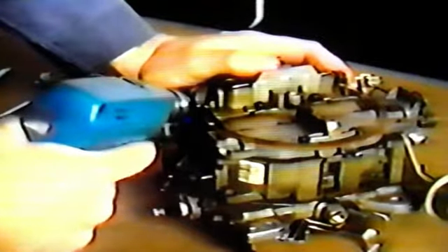While this isn't a difficult procedure, it does take a few tricks of the trade. We have found that the easiest way to remove the plug is by drilling a small hole which measures approximately 7/64. You want the hole to be in the center of the plug, but do not begin by center punching it. This could force the plug in tighter and damage the TPS screw, which is only about 2.5 millimeter hex.